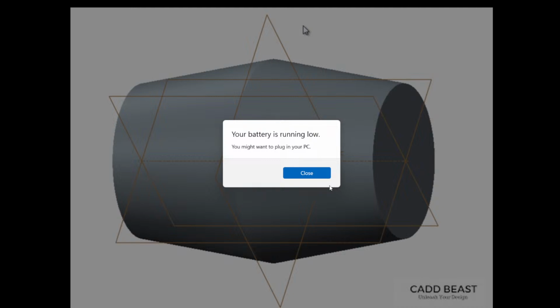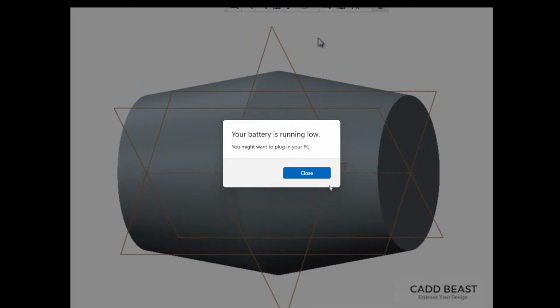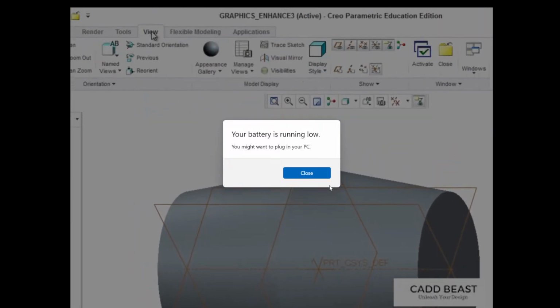You can find the name of any feature by moving your cursor over it, and when the feature pre-highlights, its name will be displayed. To turn the display of datum tags back on, go to the View tab, and in the Show Group, you can toggle the display on and off. You should also notice that new lighting has been applied to your models. New solid features will default to this medium gray color that contains lower shine and reflection than previous releases.